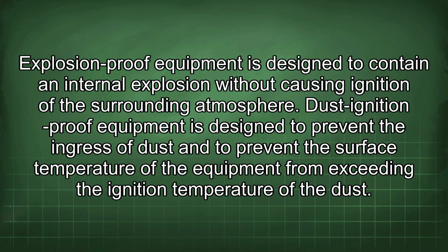Explosion-proof equipment is designed to contain an internal explosion without causing ignition of the surrounding atmosphere. Dust ignition-proof equipment is designed to prevent the ingress of dust and to prevent the surface temperature of the equipment from exceeding the ignition temperature of the dust.